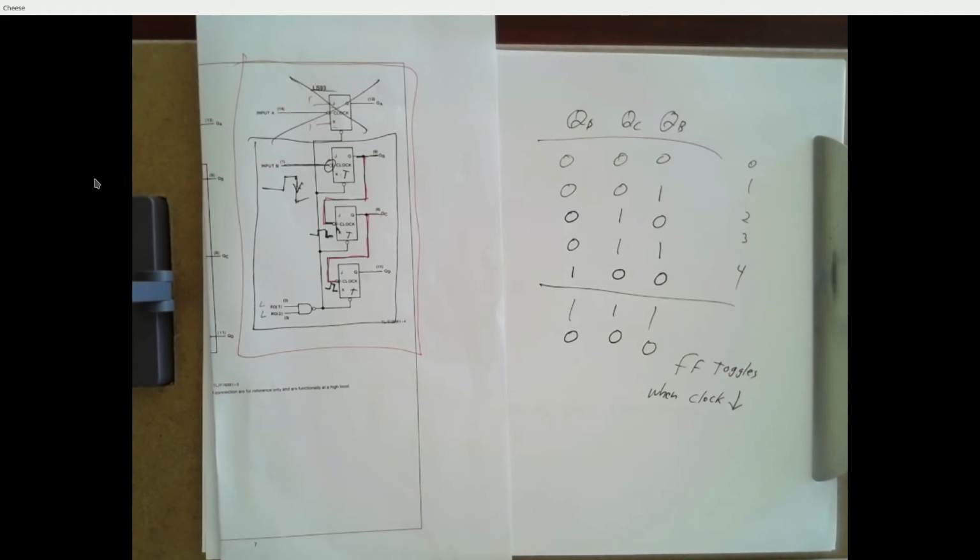And if we have a clock going over here, but that clock runs through some circuitry before it gets over there, stuff is going to happen here before it happens over there, and it's not synchronous anymore. And now you've got a design nightmare, right? So everything that we're doing from here on out works well because all these clocks happen in unison. That's the idea of a clock, right? It's like if every clock in every classroom showed you a different time, we'd have a really big problem, right? So we want to keep these clocks as clean as possible.